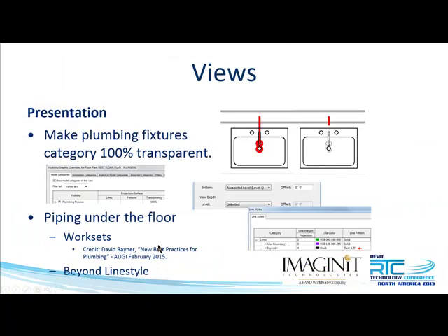All right, so this last tip on this slide is, when we first started using Revit in the CAD days, we would be working on the second floor plan. We're hooking up all these sinks and toilets. In the CAD days, we wanted to see the sanitary serving those fixtures. When Revit came along, we couldn't do that anymore. I'm actually glad I didn't know about this tip when I was doing production, because I don't really want to do it. But if you insist on maintaining that standard, this is how you can do it.